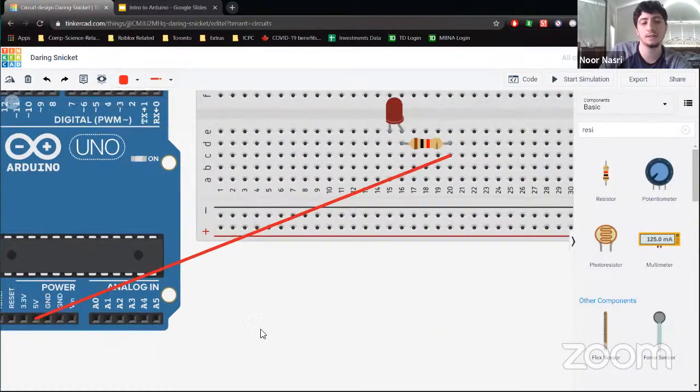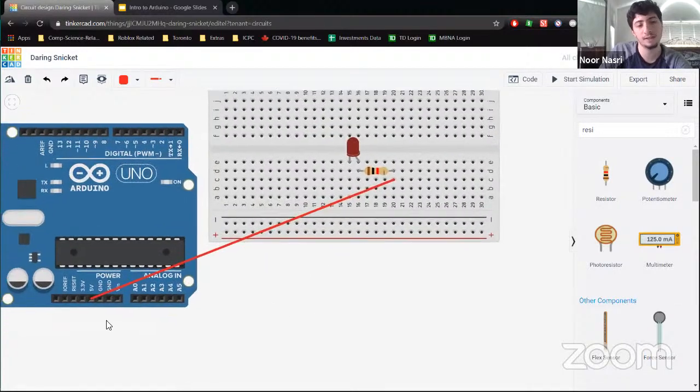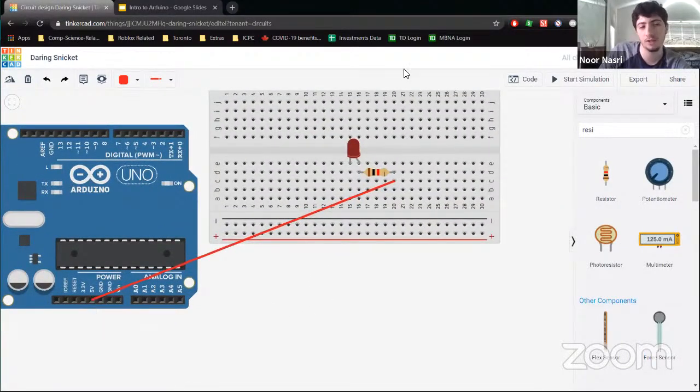Okay, so you can see the electricity is going to start here. Once we finish wiring, it's going to notice there's a 5 volt difference. It's going to go through here, come to this column, and go up through the resistor, so it's having resistance, go up to the anode, through the LED, and then we're going to ground this. All right, and then I'm going to label that black. Now you'll notice that we're not using these. We want to start using them after. So check. All right.